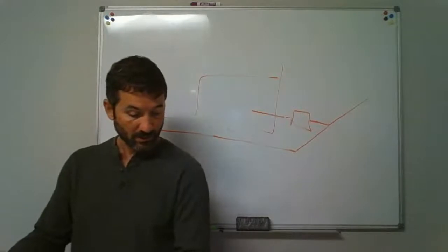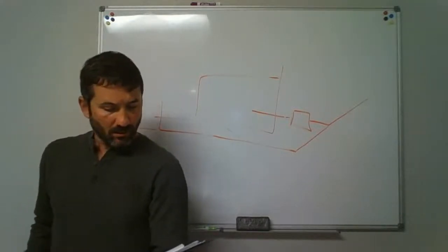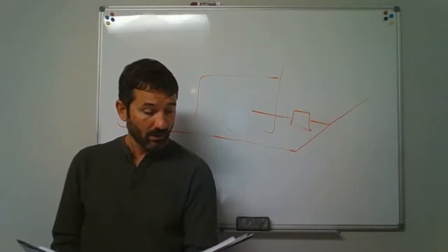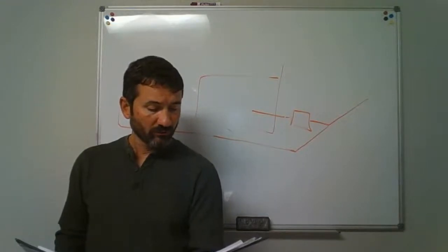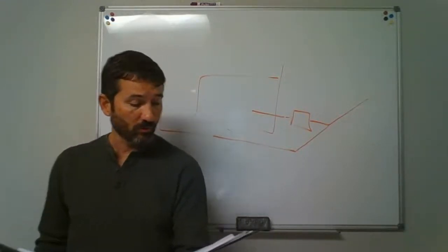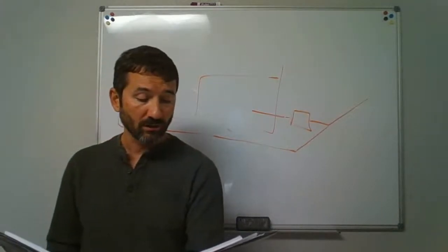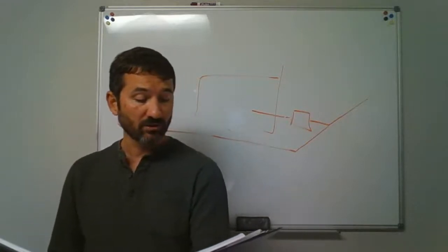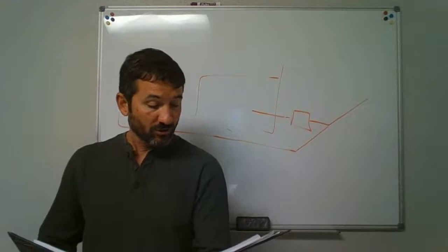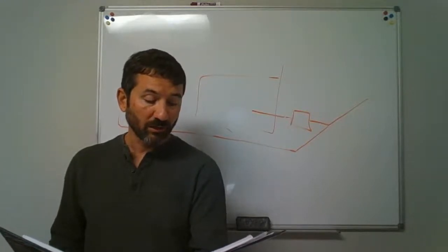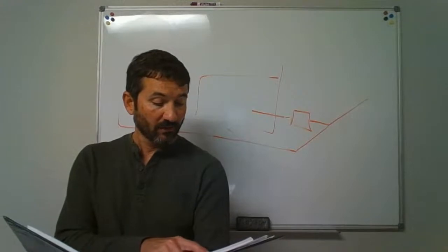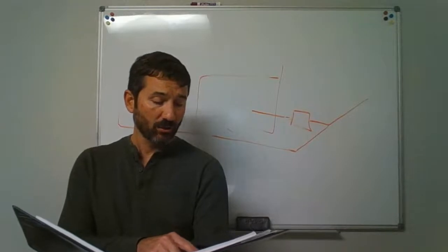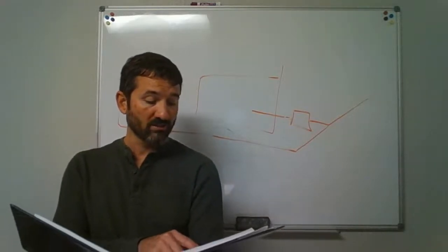Okay, let's see what else we got. Grease interceptors and automatic grease removal devices required. A grease interceptor or automatic grease removal device shall be required to receive the drainage from fixtures and equipment with grease-laden waste located in food preparation areas, such as restaurants, hotel kitchens, hospitals, school kitchens, bars, factory cafeterias, and clubs. Fixtures and equipment shall include pot sinks, pre-rinse sinks, soup kettles or similar devices, wok stations, floor drains or sinks into which kettles are drained, automatic hood wash units, and dishwashers without pre-rinse sinks.